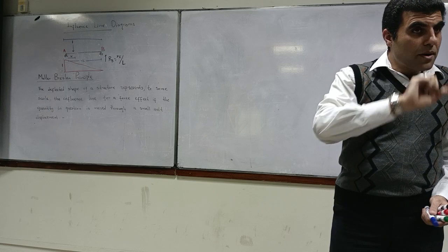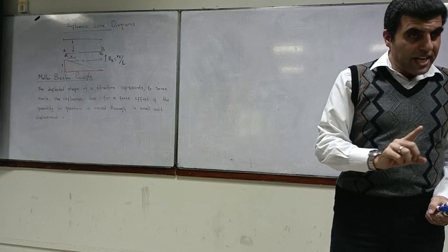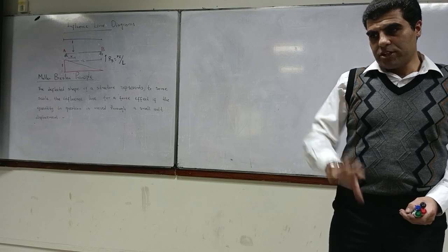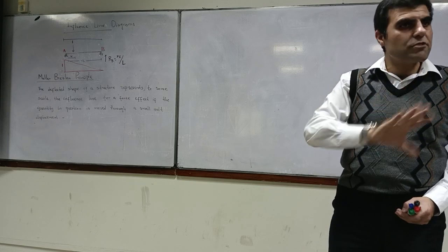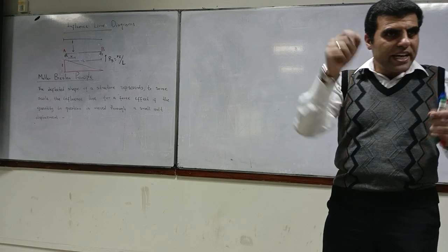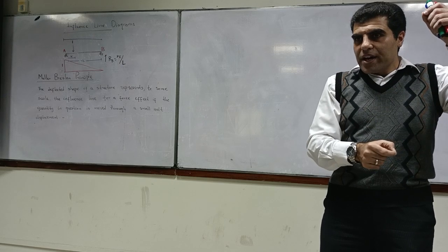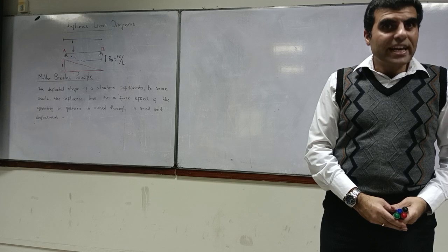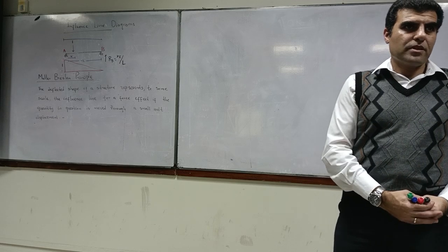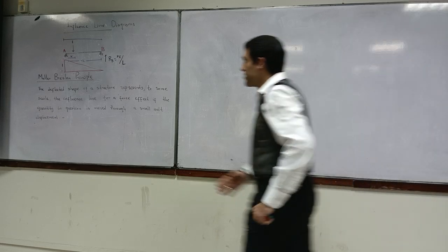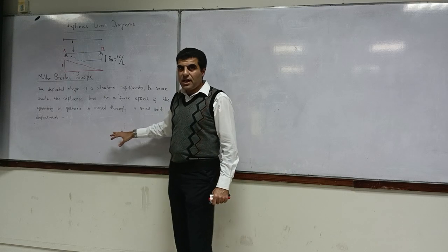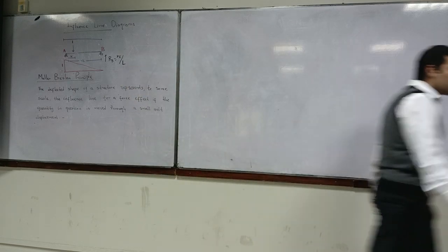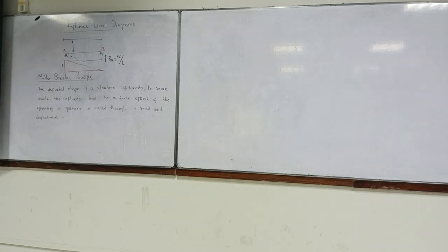But we are doing it currently for the determinate structure. For determinate structures, as I told you, the influence lines are linear. You can easily move it and find out your influence line diagrams. For the indeterminate, it's not linear, but that comes later. That's not in your current scope. So that's how you apply your influence line diagram. Ask me any questions.